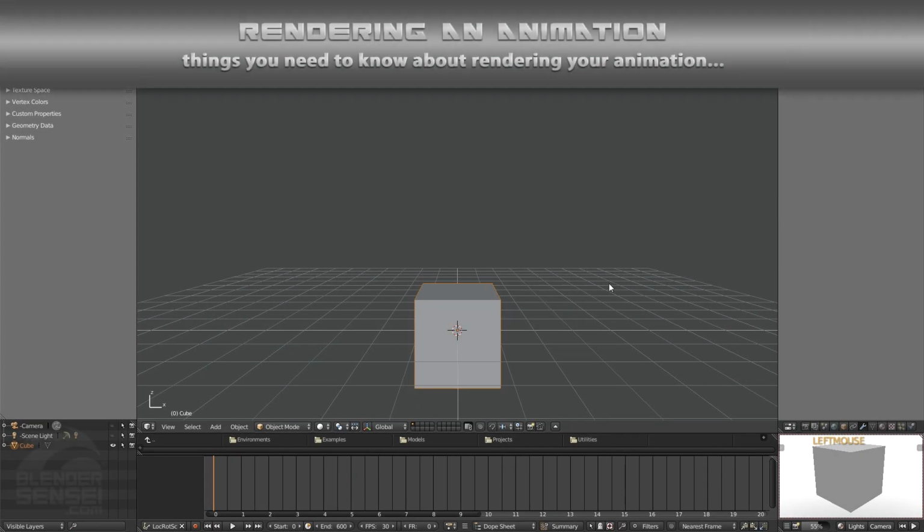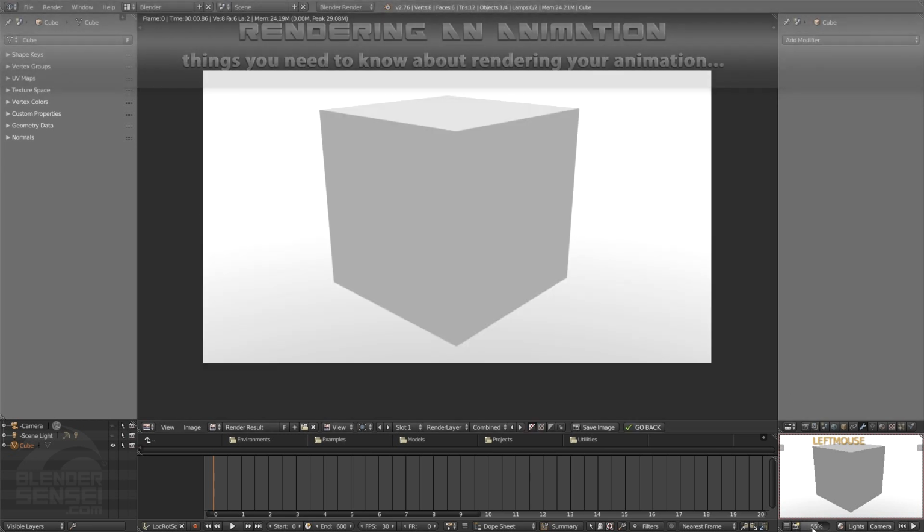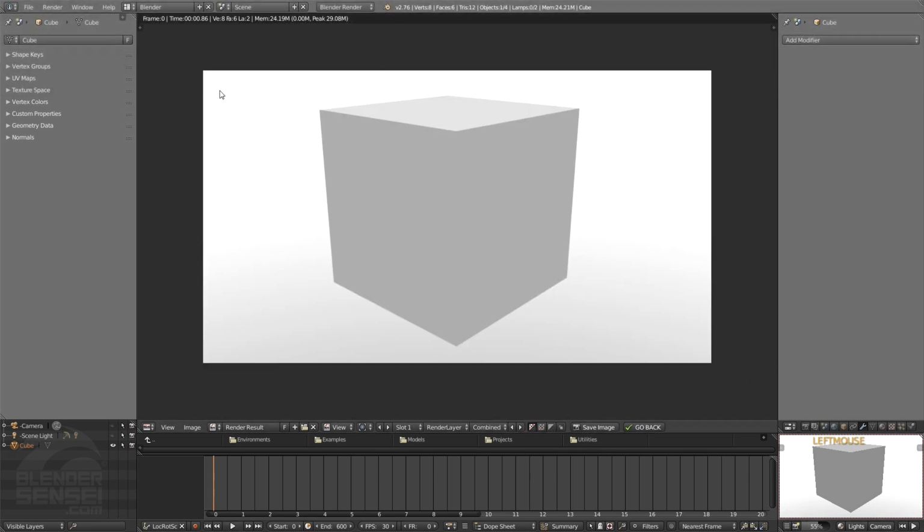So we can render our scene by pressing this button down here if we just click that. And of course this slider right next to this controls the resolution being used to be rendered. By default the resolution is 1920 by 1080. So this is 55% of 1920 by 1080, which gives us obviously smaller than 1920 by 1080, but renders much faster and is helpful for us doing tests.